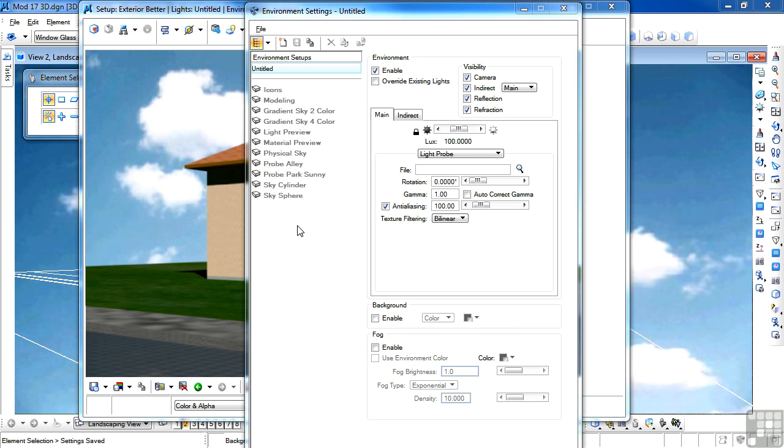What you see is lit by that environment, and Luxology can reproduce most aspects of an environment quite faithfully. An environment can only be applied to an interior scene if there are transparent or translucent openings in the exterior walls that allow environment light to enter the scene. An environment setting can be used to indirectly light a scene without the use of installed 3D lights. However, installed 3D lights can also be used to generate specific shadows in conjunction with environmental lighting. In general, environment lighting gives a soft ambient light.